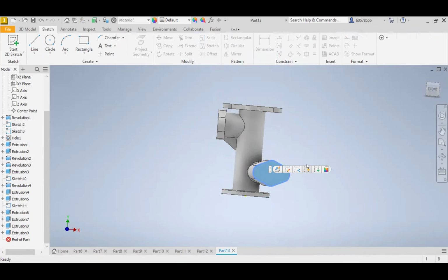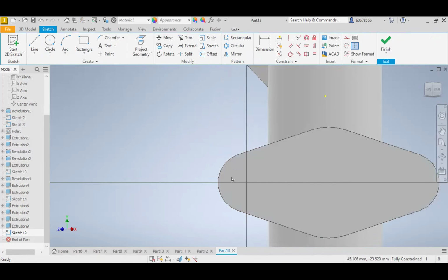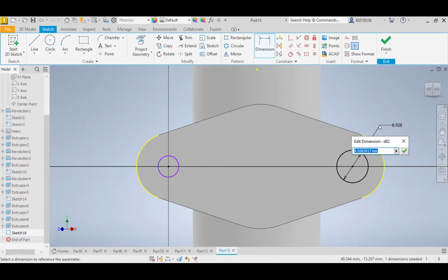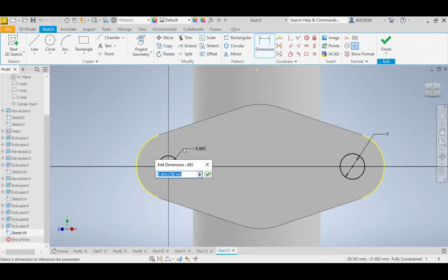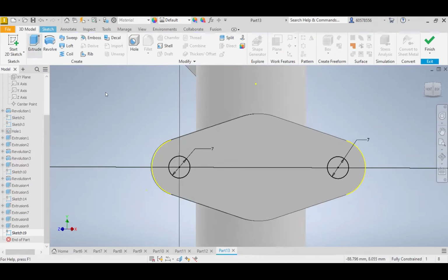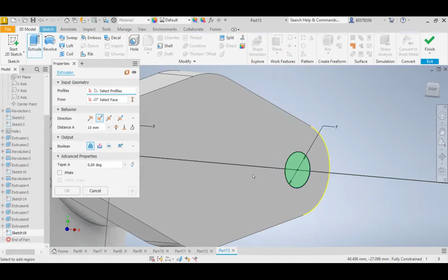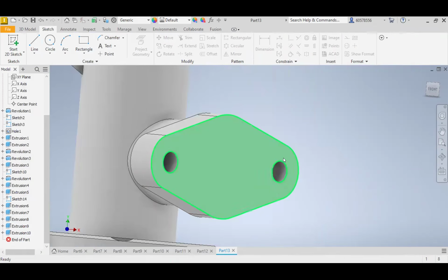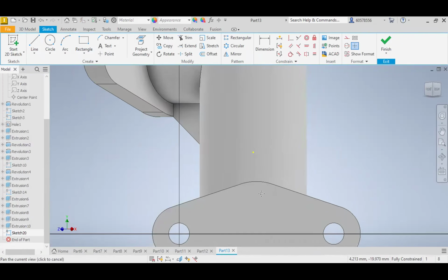Our whole back, we need our hole. Let's rather start with the two small holes. We are almost done. I believe this should be the last part. Otherwise, the gaskets, that should be nothing. The gasket and the washer. So the small holes, the diameter is 7, and it's 2 of them. We extrude and we are cutting it through just like this, and one more sketch there.